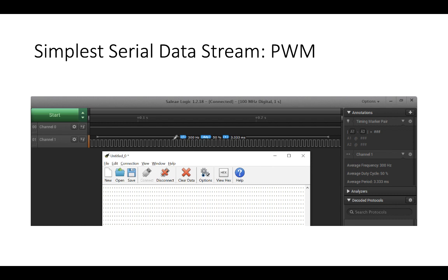So today what we're going to show you in the first instance is a series of pulse width modulated bits, which is basically meaning the voltage goes up and down, up and down, up and down. Half the time it's on, half the time it's off. Half the time it's up, half the time it's down. And those bits that are going up and down are being sent from the microcontroller, and you can see the visualization within this logic analyzer where I was measuring the voltage coming out of the microcontroller. And then it's sent over, in this case, a USB line into a PC, right?